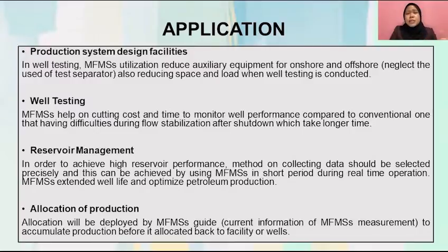Unfortunately, there is no single instrument that can measure different phases of flow rate, and it is necessary to combine several devices in an instrument to calculate the specific flow rate from combined reading. That's why MFM is widely used or introduced to the onshore and offshore production.